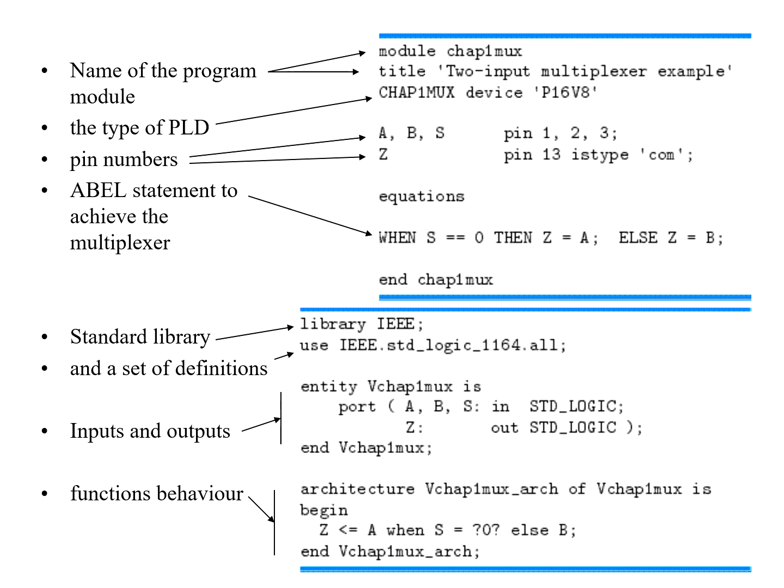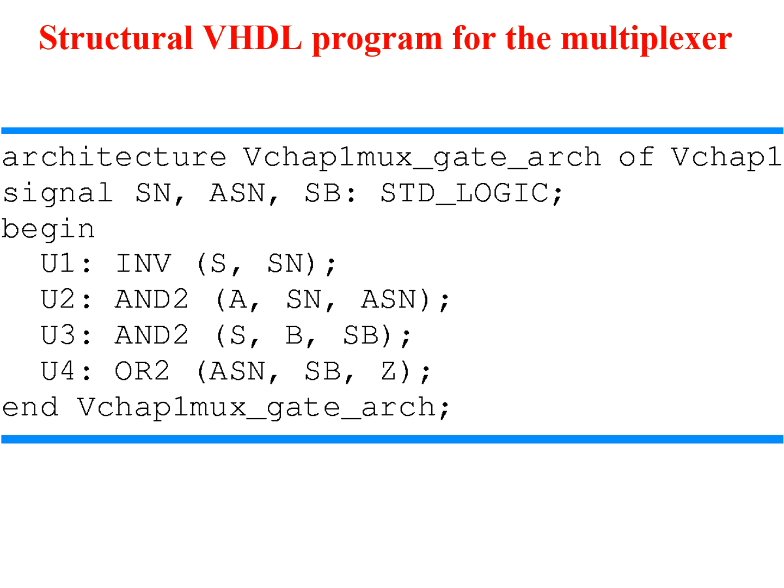So in the hardware description language, we are going to design by setting the library values, and according to the library values, we get the input and output ports, and then the functional behavior is designed with the function Z equals A when S equals 0, else B. After completion, we get the input value, and then the signal acts as a switch and produces the output data.